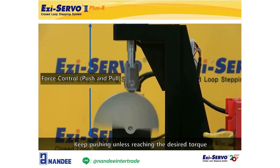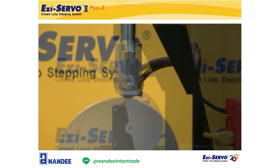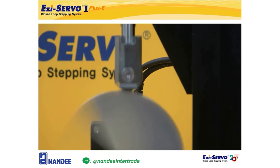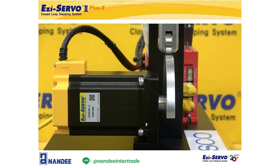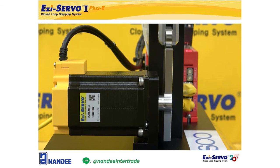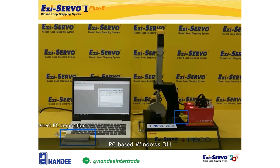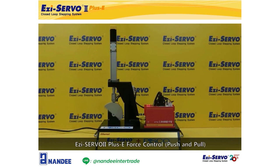In the position control method, when the lower half disc moves, an alarm occurs because the position value of the upper motor changes. However, if it is driven by force control, it does a constant pushing motion with a certain amount of torque rather than a position value, so an alarm does not occur. This is a necessary control method when the target position value varies depending on the object, for example, when picking up objects of different sizes with a gripper, or when fastening objects with different heights.